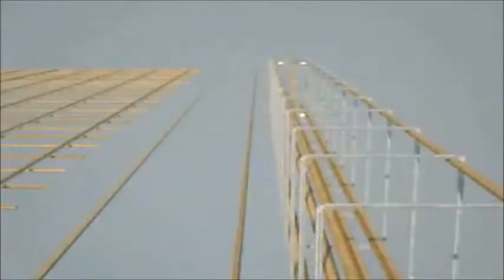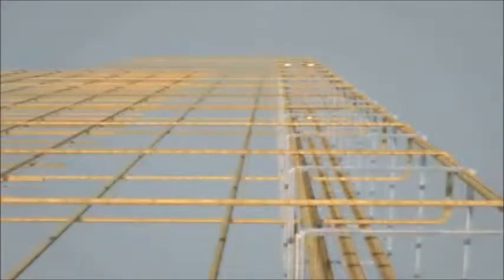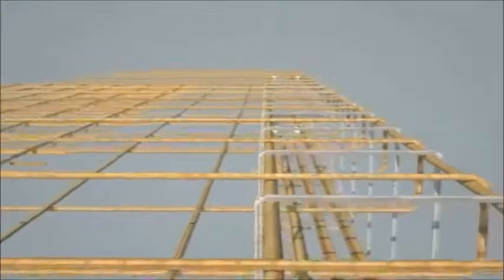Now, here will be the animation of how the steel bar and steel fabric reinforcement were arranged and placed inside the ground floor slab. If the ground beam depth is larger than the depth of the ground floor slab, then there is no need for the construction of formwork for the ground floor slab.